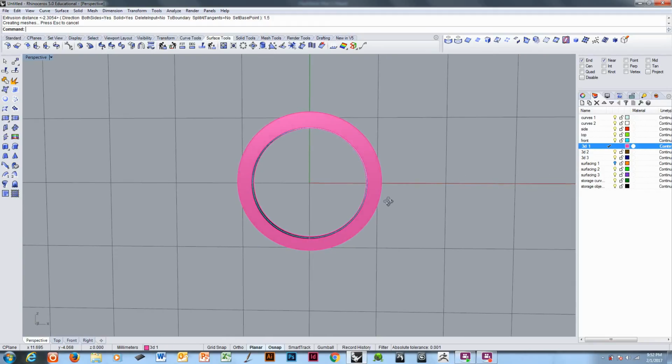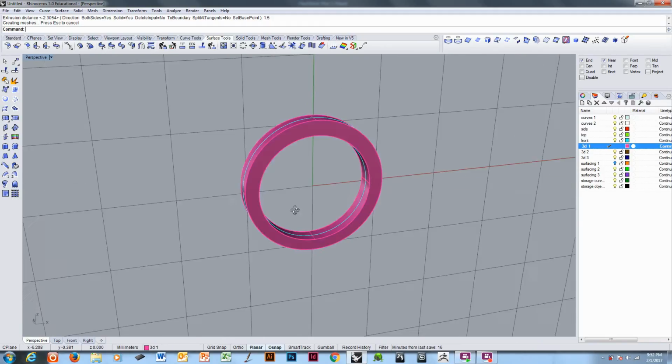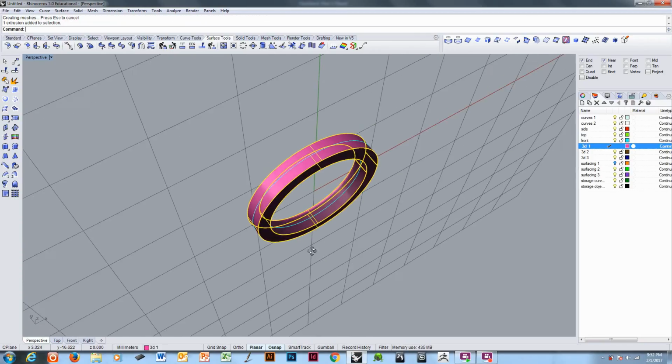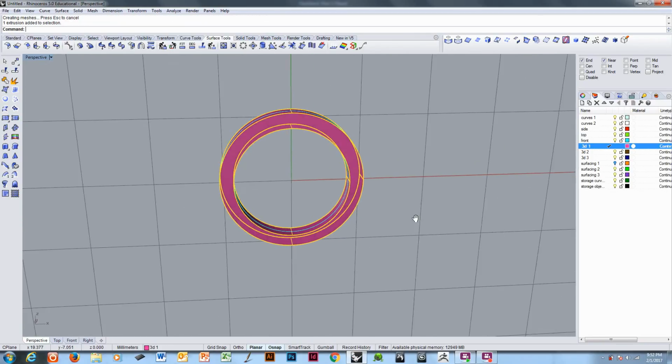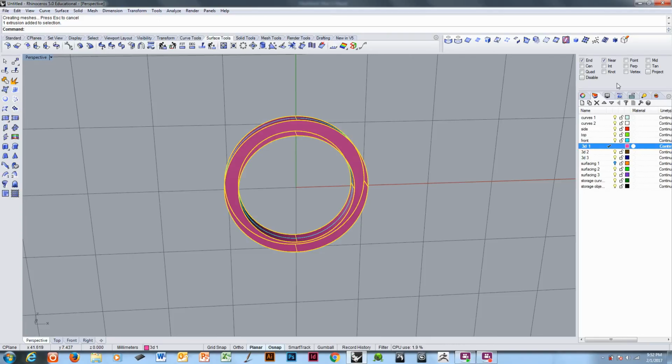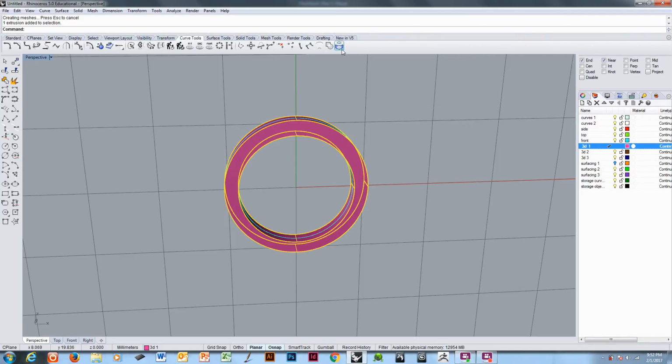for maquette purposes. Now I need to do a center line. I want a center line going each direction on this shank that I can use as a design reference when I'm drawing later in 2D, either with a pencil or in a graphics program. I'm going to use the section tool. To get this tool, I pull this tool bar off to the side in Rhino when I'm working. You normally find it as a cascade, a pop out from the curve from objects button, and I always just take mine and set it over to the side here, and then I drag it over so I have enough room to see them all.